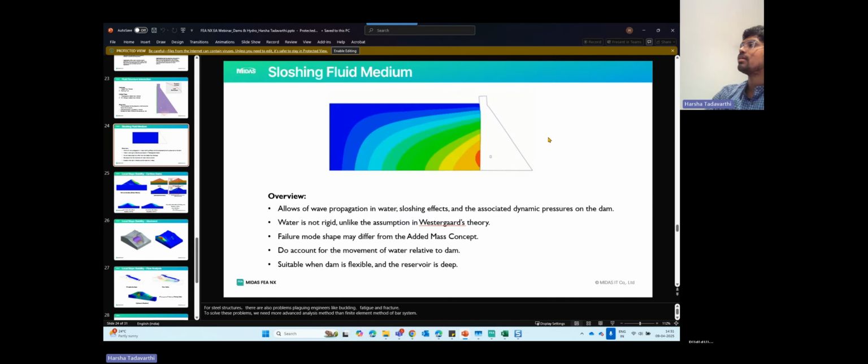So here in the analysis works tree, you can find the LC2 load combination getting applied. So what I will do is I will go to the loading tab and only activate LC2 rather than activating all the loads, only activate LC2, which is the load combination set that I had created.